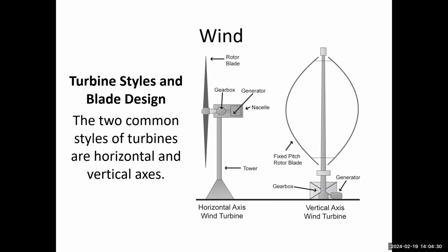You have the giant wind blades, and they're coming in all different sizes and shapes now, right? They spin a gearbox. The blades spin fairly slow when you see them out in the world, kind of just lumbering around. Then you gear that up into high RPMs. A big gear spins a little tiny gear, and that little tiny gear is really booking, so you can get the RPMs as high as you need to spin the generator.